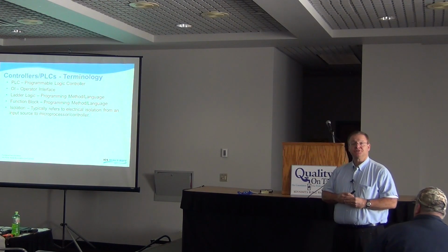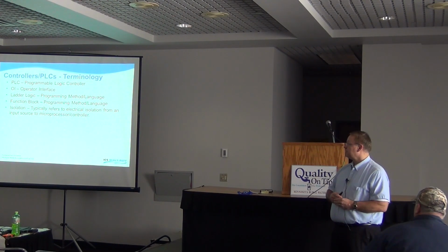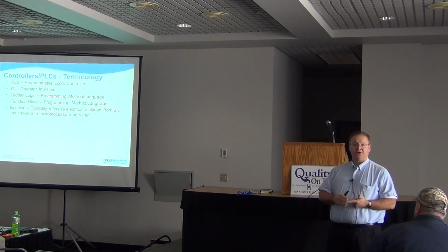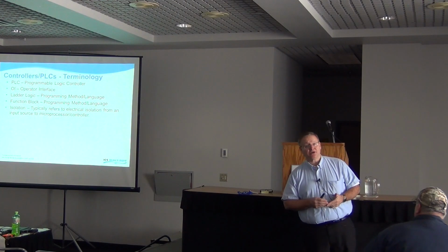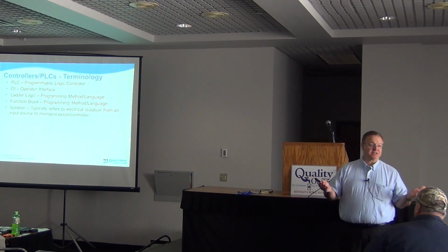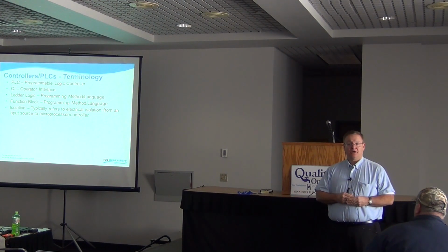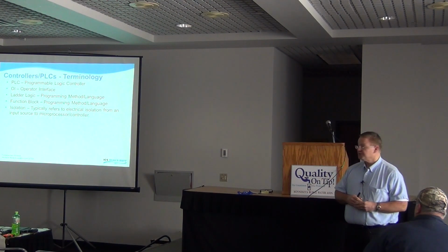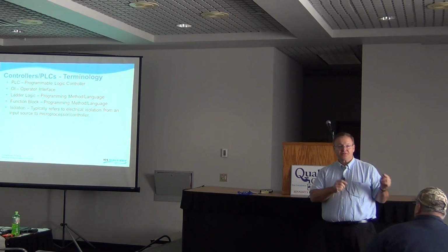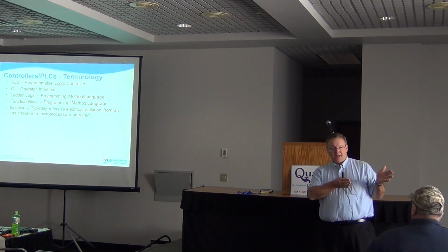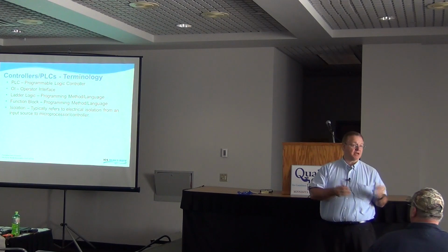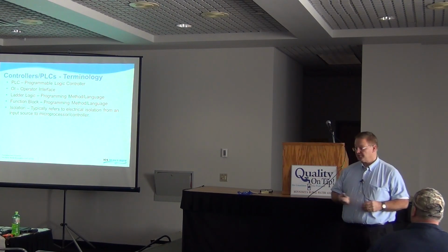You'll see isolation used a lot in SCADA systems, and basically what isolation does is it typically refers to electrical isolation because of the noise and the transients and the ground loops that can occur out there. You like to have isolation on your inputs into your PLC systems or your SCADA systems, just to make sure that you're not getting erroneous, high-level electrical spikes coming into it, or even sometimes surges that can come in there and damage those inputs.